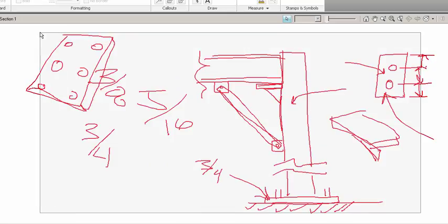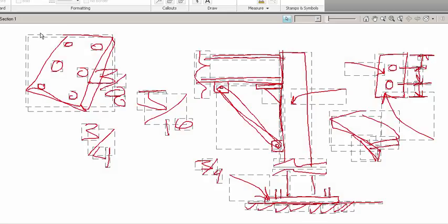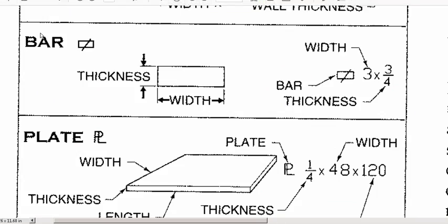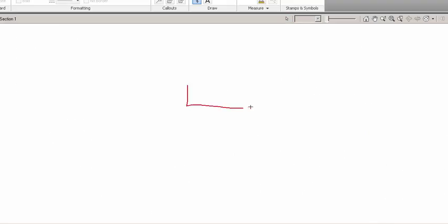A lot of times steel plates are used in staircase design, exterior stairs. Diamond plate is used a lot of times for treads on your staircases. If I'm going to actually make a steel staircase, I might do something like this, where I take steel plate and bend it to make this shape. Actually, we'll add a little toe catch there too sometimes.